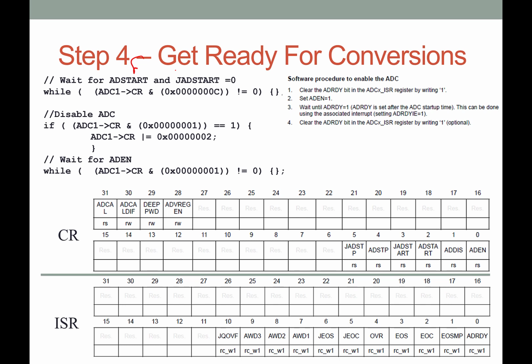And you can see here, for example, the A to D enable, it's comparing the control register with 1. Okay, here's the control register and the bits, and it's ANDing it with 1. Well, 1 is putting a 1 in that digit right there. And it's saying, okay, if that ANDed with 1 is not equal to 0, then keep going through it.